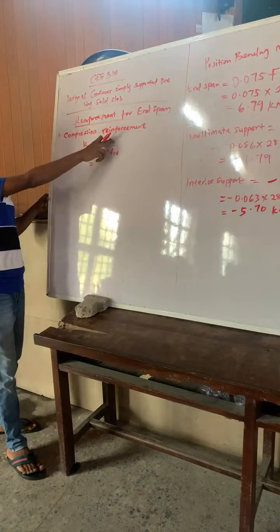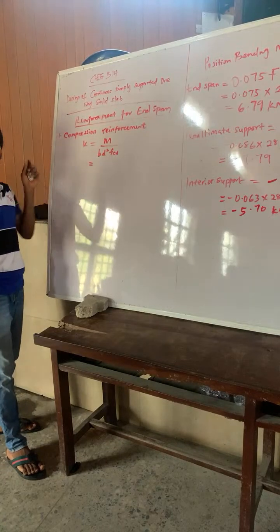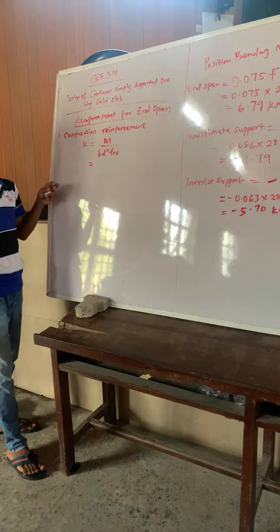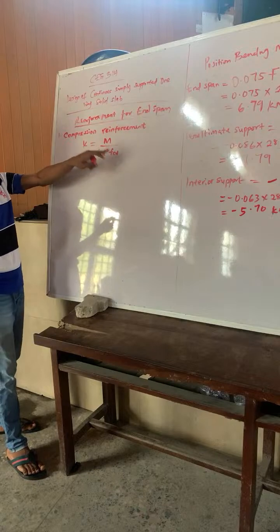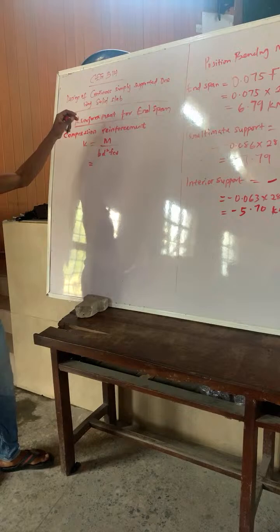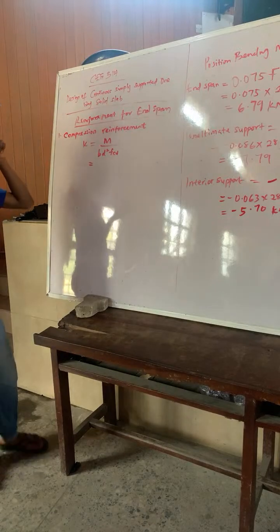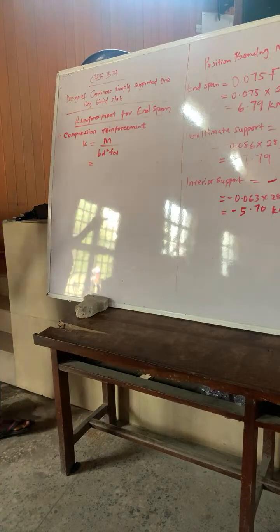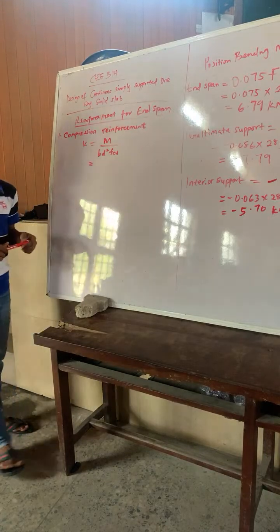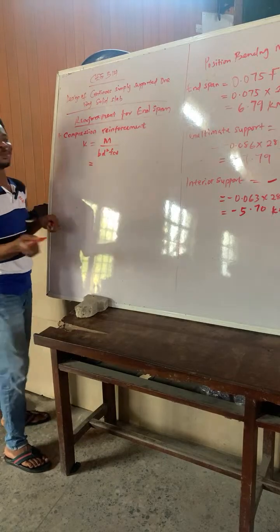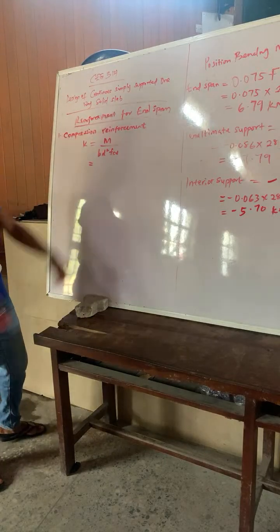So what's our M for BD square FCU? M is our moment. B is our breadth, which is 1,000. Take it as 1,000 millimeter. FCU is the characteristic strength of concrete. Check your BS code. You see all the formulas that we are using in the BS code. Yes, please know it. No, it will not be given. Cram it.